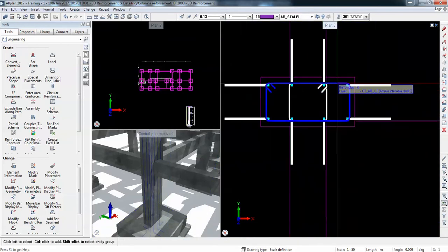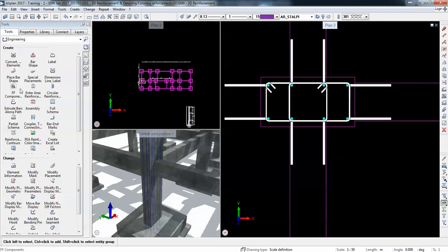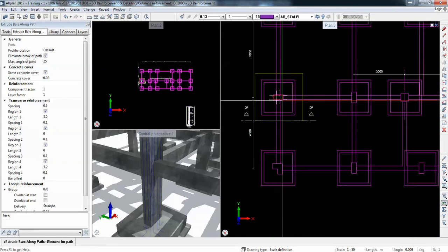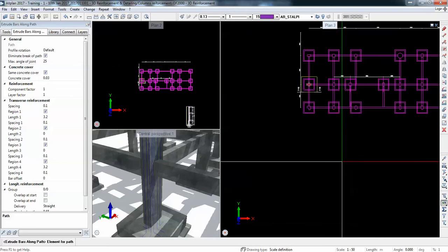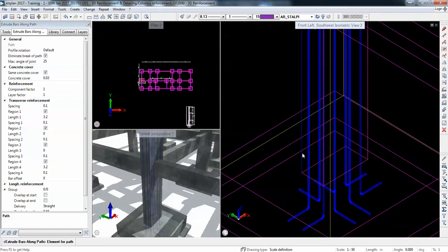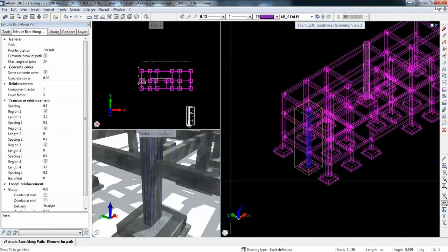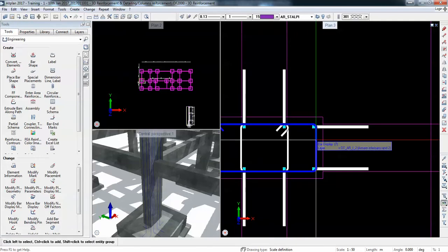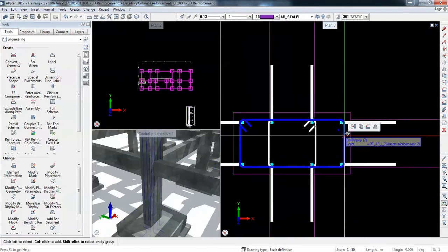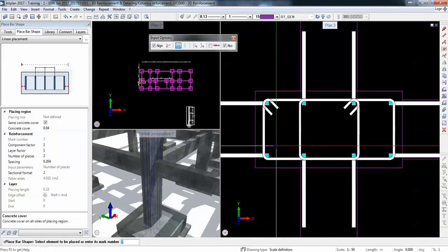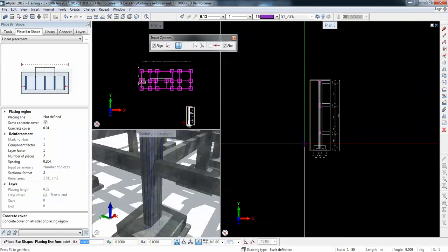And once I create this placement, I will do this, extrude along a path, select this element, and the element for path will be this column. But I don't understand what this error is about actually. The function is quite new, but I'll just, I don't know, if I placed it traditionally, so I place them normally on a section.